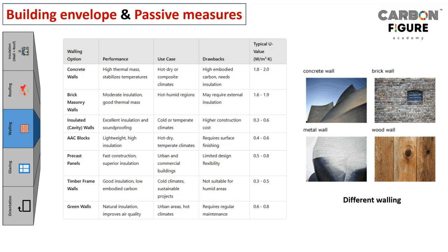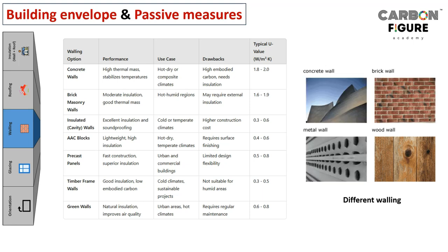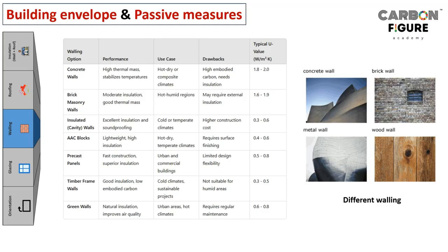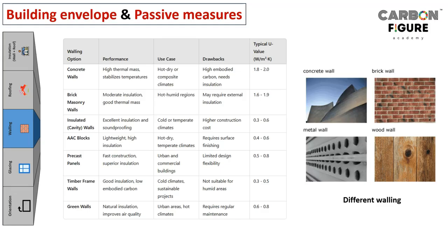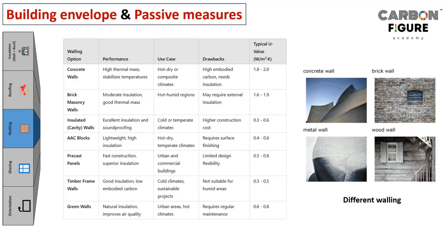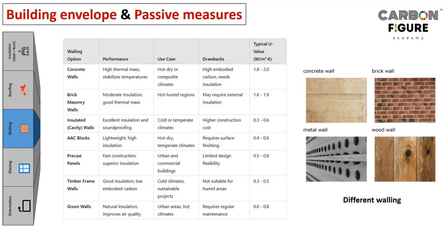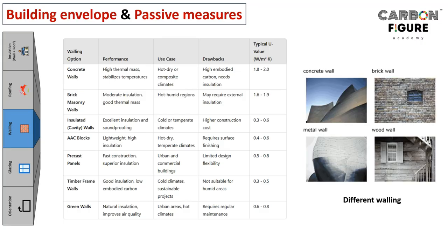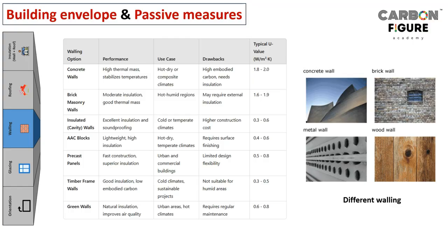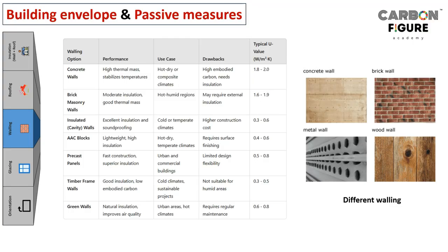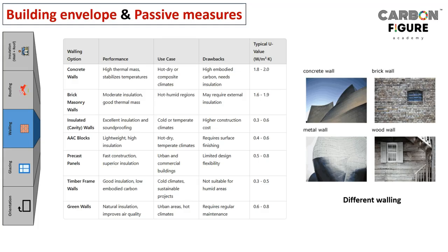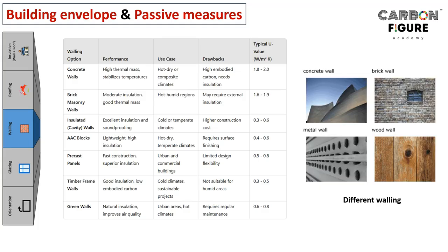Alternative brick products are coming up in the market. What you should ask is whether they satisfy the compressive strength requirement, because that is fundamental. Then you can ask about the U value. Okay, you are producing your brick with some alternative or waste material, that is fine, good, congratulations, but what about the U value, right? That is very much important.